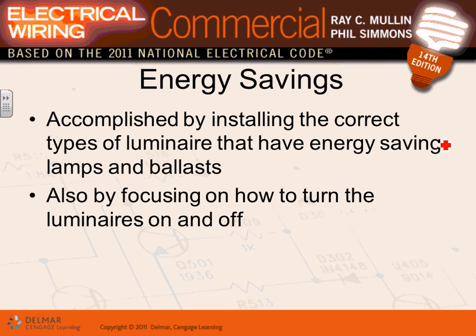So energy. The key word, guys, is energy and energy and energy. ASHRAE 90.1 2010 will be adopted soon in Minnesota. It will require you to have a lot of auto means of controlling your lighting system, such as an occupancy sensor or non-occupancy sensor. And you guys heard about the whole change. So the whole idea of this lighting control system is to save energy. Now, a byproduct or another major part is to be able to control your lights, turn them on and off remotely, making it easier for people.